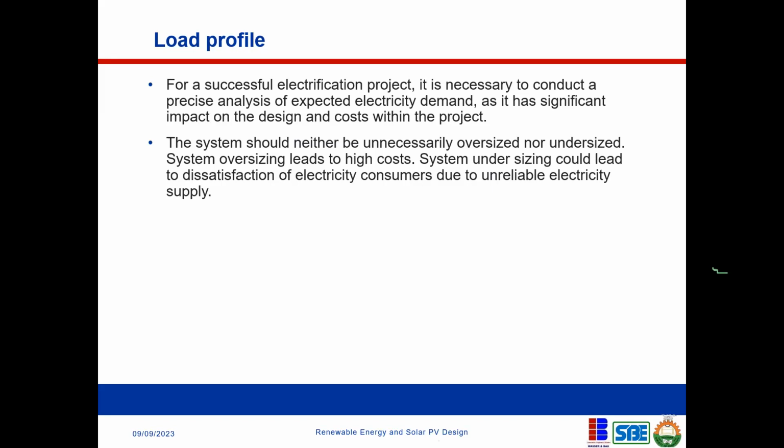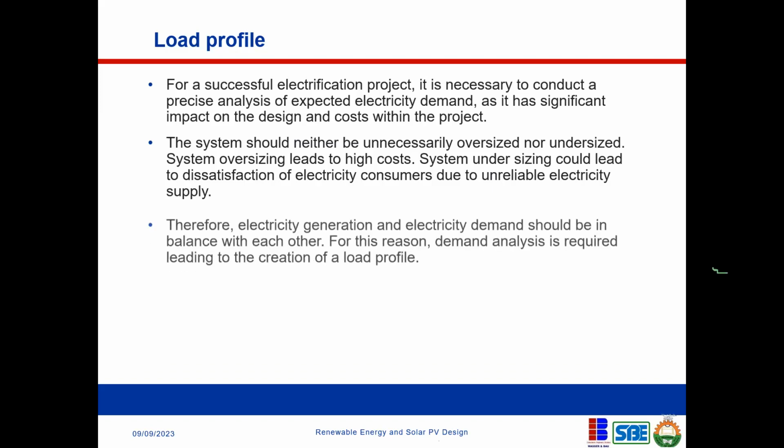Even when you're sizing your generator, it's a very big mistake that we make when we are sizing our generators in Nigeria. We look at the peak and we do not investigate the cost of that peak. Maybe the peak can be shifted. Maybe there is a pumping machine that comes on when cooking is going on in the afternoon. When the electric cooker is on in the afternoon, somebody owns the pumping machine, and it creates a spike in your profile. Let me show you what a load profile is.